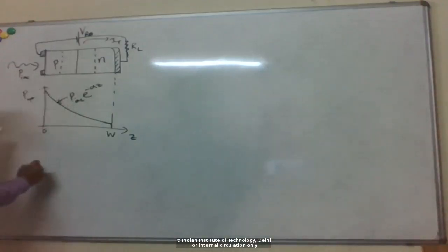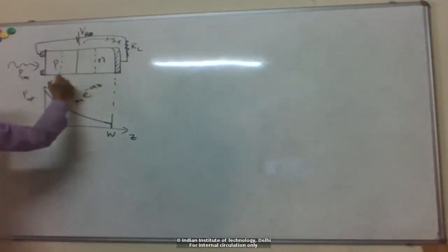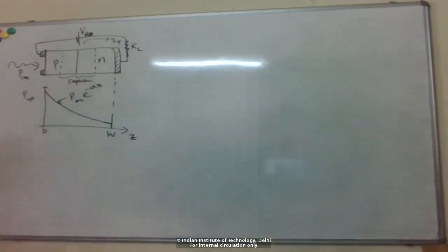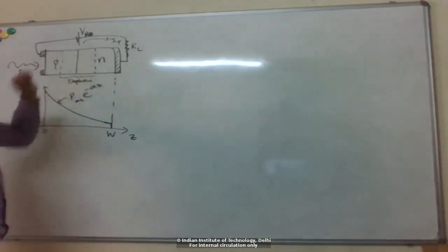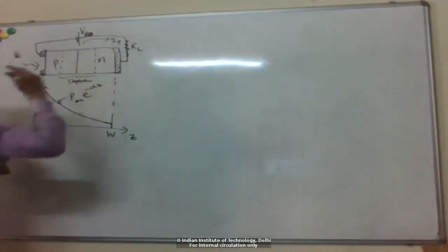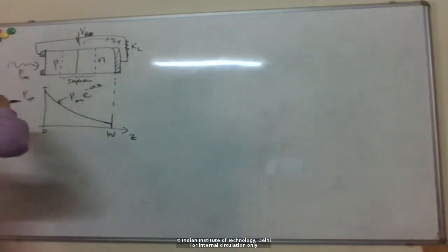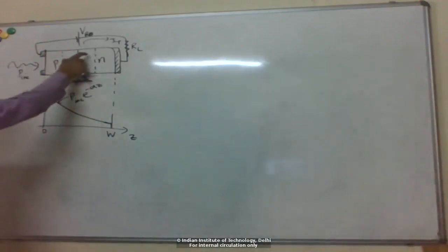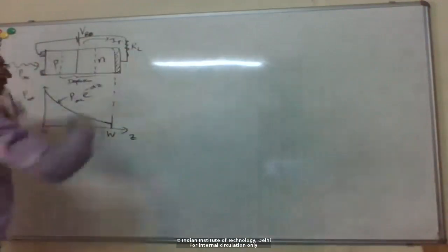Right. So if you look at the band diagram within the device, these dashed lines here, of course, indicate the depletion region where there are no free carriers within the device because of diffusion of electrons into the p side and holes into the n side. Right. We have this depletion region. And this depletion region actually gets widened because of this reverse bias which is applied. Right? So under no bias, there is some depletion region width. So, for example, when we had forward bias for the sources, the depletion region actually shrinks a little bit. When you apply reverse bias, the depletion region actually widens.